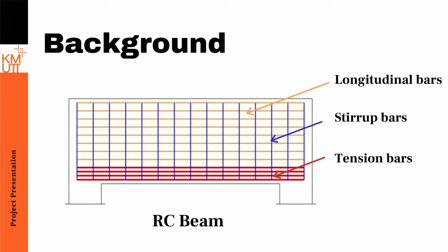For concrete structure, it is designed as a general reinforced concrete beam in strength design method. Additionally, there are some recommendations from the cooperating company for typical detail. The design consists of flexural, shear, and skin reinforcement, and this shows the positions of each rebar.